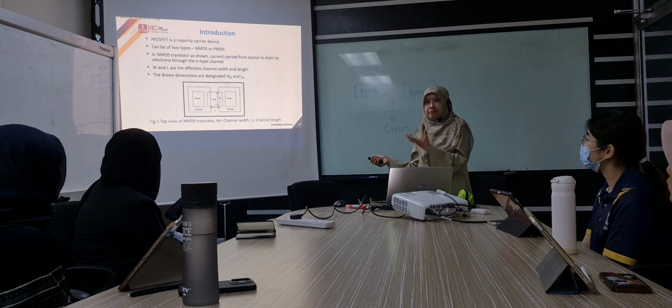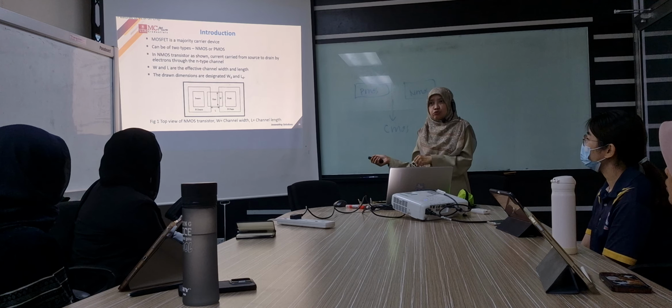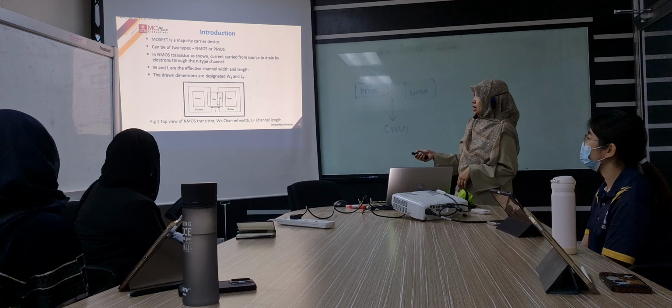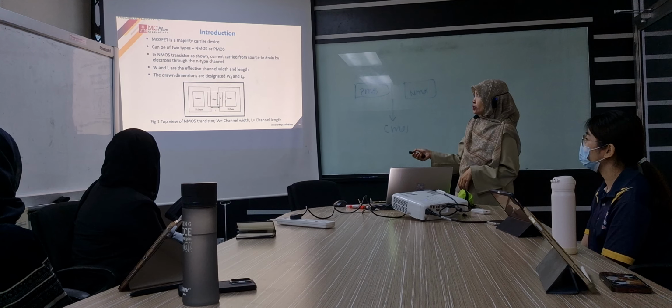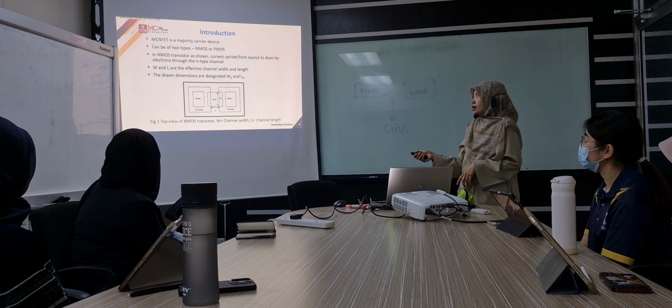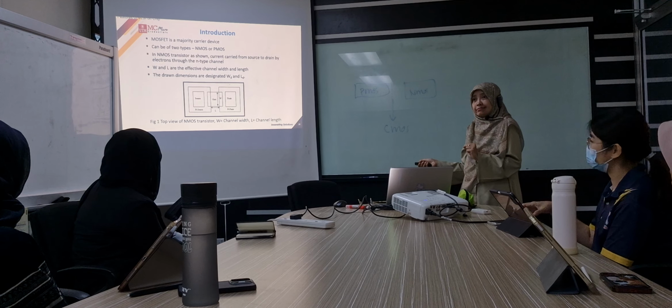These two will impact the design performance in terms of IV characteristics and switching. This is called channel length, and this one is called the width size. So, we need to size the width, then we can have different currents.